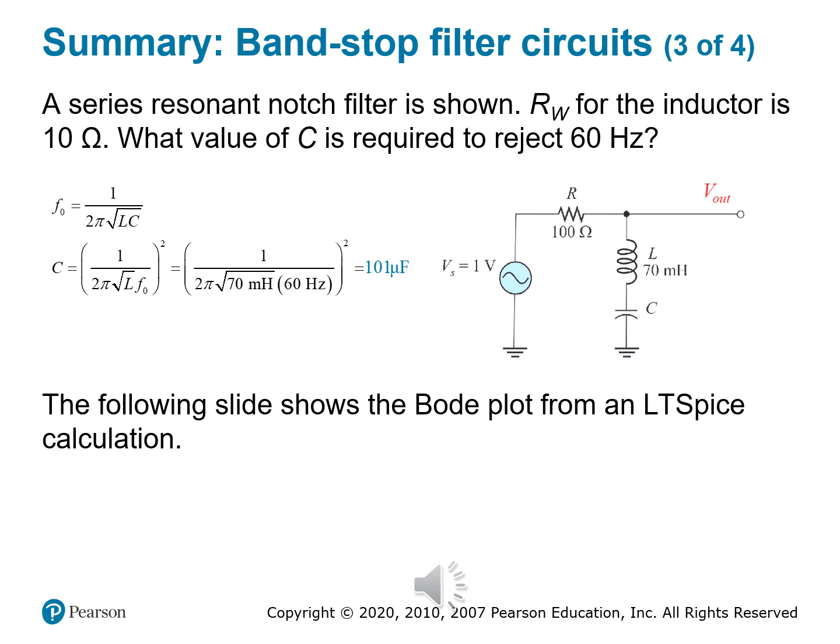Band stop filter circuits, slide 3 of 4. Welcome back to Filter Frontiers. In today's Design Lab segment, we're crafting a series resonant notch filter. Notch filter and bandstop filter are the same term, used interchangeably. If you think of notch like you're just notching something out, it might give you a better visual for stopping a certain band range of frequencies. It's a tool for knocking out unwanted frequencies like the 60 hertz hum, or the 50 hertz if you're overseas, from your signal path.